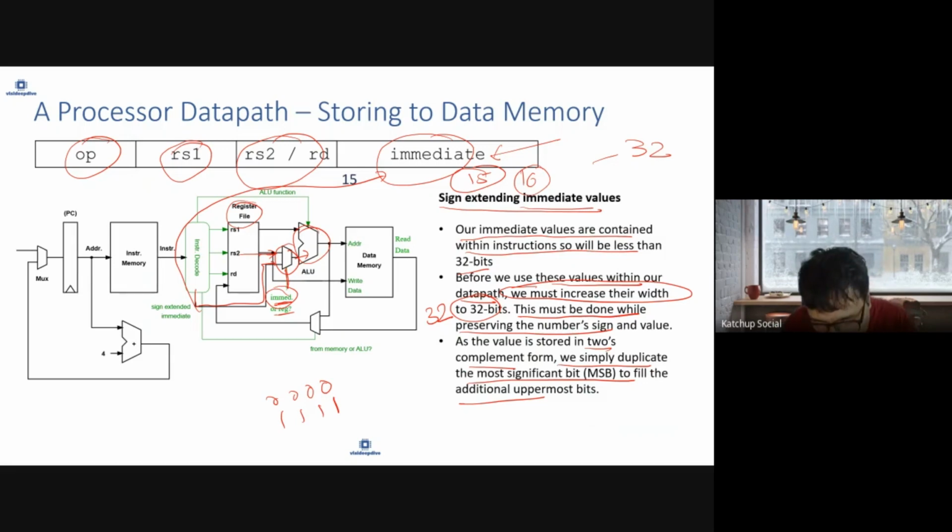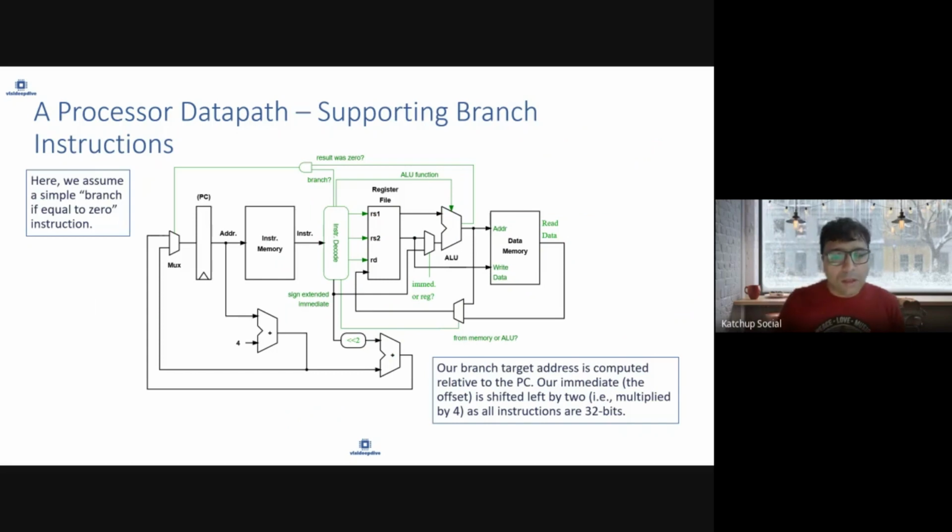And now we have added support for immediate instructions also. We have added support for directly writing into the memory or reading from the memory, and we move forward in designing our simple processor. Now we can also support branch. A branch instruction is nothing but similar to a jump, where you want to go to another instruction rather than loading from the program counter. We had said we'll do our branch instruction where you are jumping to a particular value.